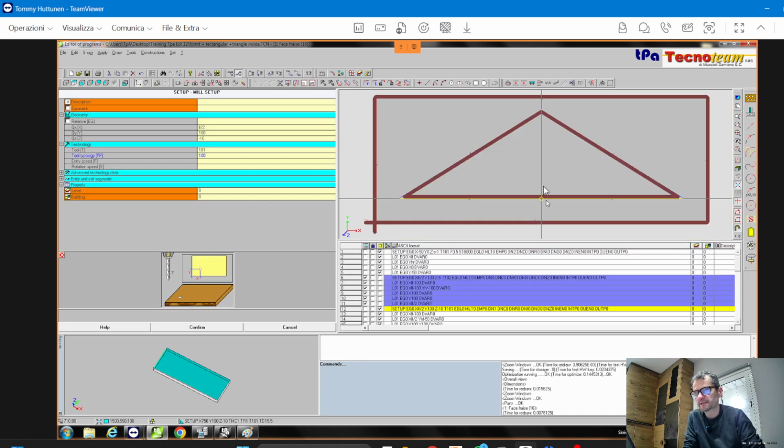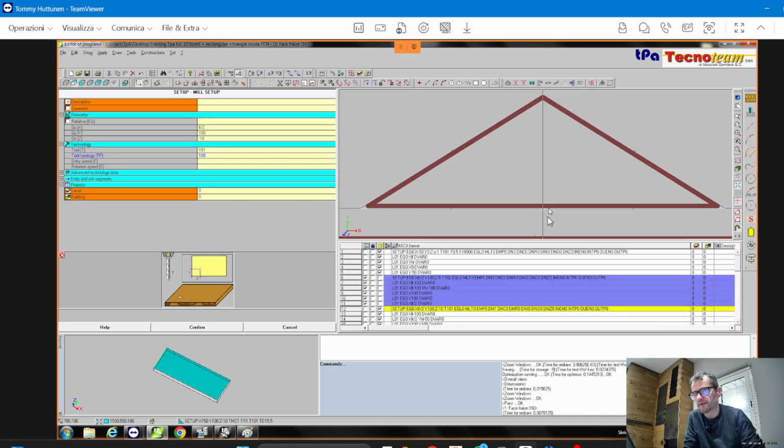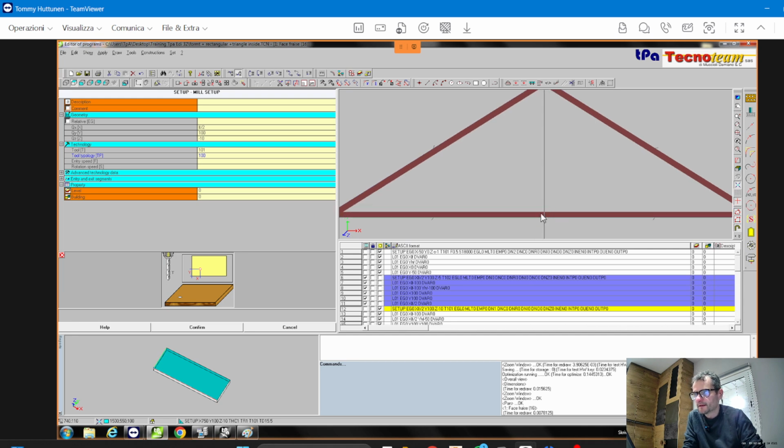I want to explain. For example, if I go inside in the triangle, in this point, you can see something after. For example, a little bar. The tool can bar a little bit the wood, because I must go down slowly. And the temperature of the wood can increase and increase also if the knife is not good. Or you can have some tool that doesn't have any kind of knife on the edge. So it's not possible to bore. So I can do several ways to fix this problem.